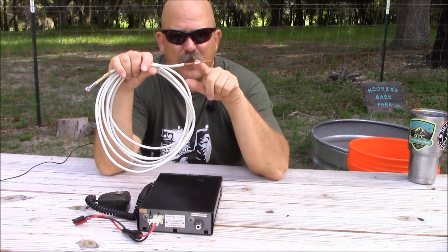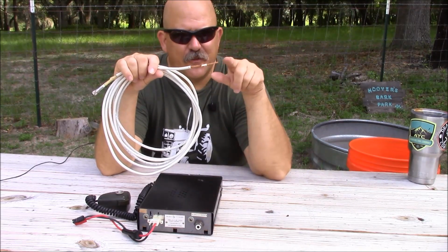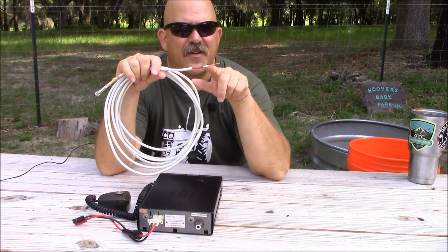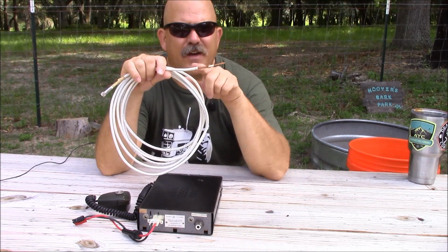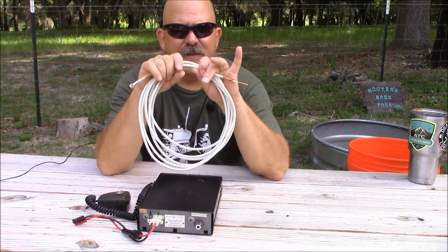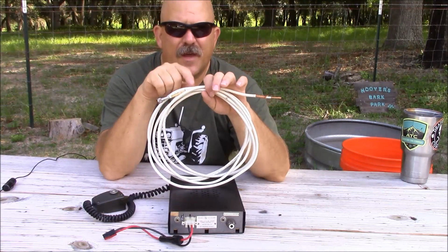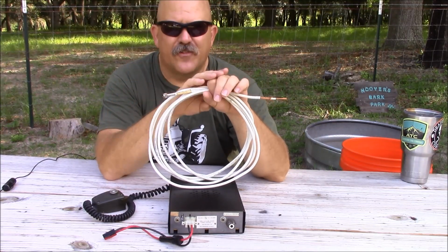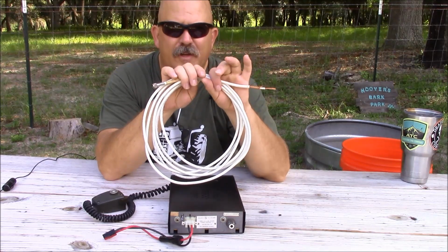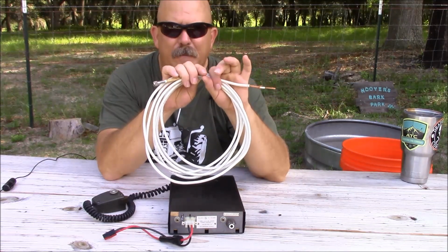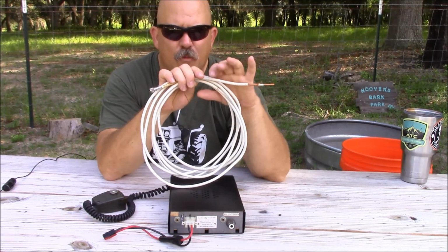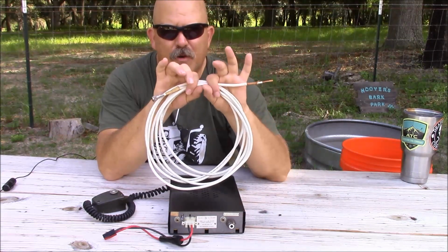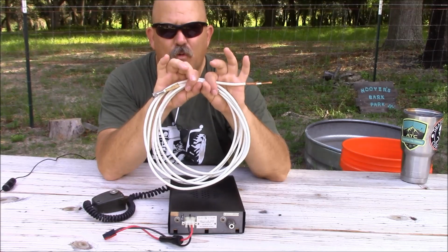And our typical coax cable, those of you who've been watching this are fully familiar with it. You have two conductors, they're separated from one another by a dielectric, and the outside of the cable is insulated with a jacket. It's important to remember that coaxial cable is considered to be an unbalanced feed line, meaning that it has a relationship with ground. And typically coax cable has an impedance of 50 ohms, which our output in our two-way radio is looking for, a 50 ohm load, so it's a perfect match for our equipment.